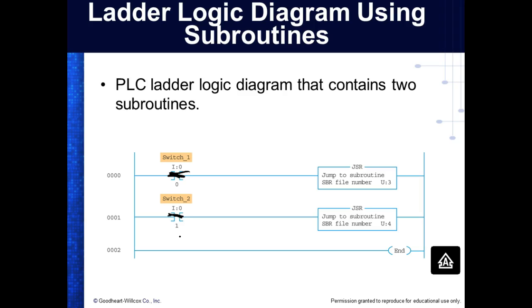Well, this is the end instruction. At the end of a ladder, you don't put any decision making in the end. It just tells the computer that that's the end of this scan cycle, and what does it need to do? So what does a PLC do? What is that PLC doing all the time? Normally, if it had nothing to do, it would just scan like this constantly.